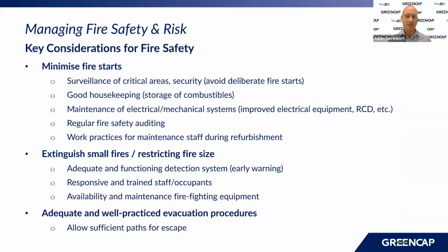It's underneath the building fire safety regulation, and annually that person, who's the fire safety advisor, has to do an inspection that includes all of the extinguishment equipment, the maintenance, egress paths, the lighting in the building. It goes through everything. I think it's fantastic, and just for everyone's knowledge, it was implemented after the Childers Backpackers fire. It's something that is hugely worthwhile in the way that it covers off everything. We can show the things that are non-compliant with that check and fix them before we have those emergencies occur, to better prepare ourselves.